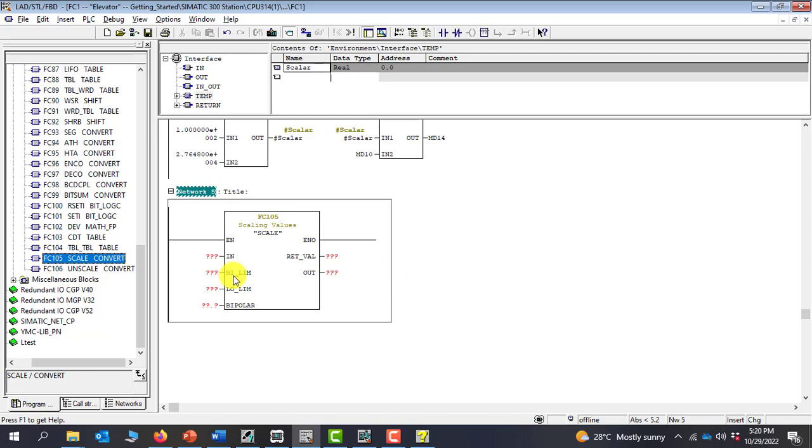And then we have the high limit for the conversion that you have to do. The high limit will take the engineering units that you want to convert this input signal into. In the example we did in the previous tutorial, we were converting weight, which is between 0 to 100, which was converted into an electrical signal and then into numbers between 0 to 27648.